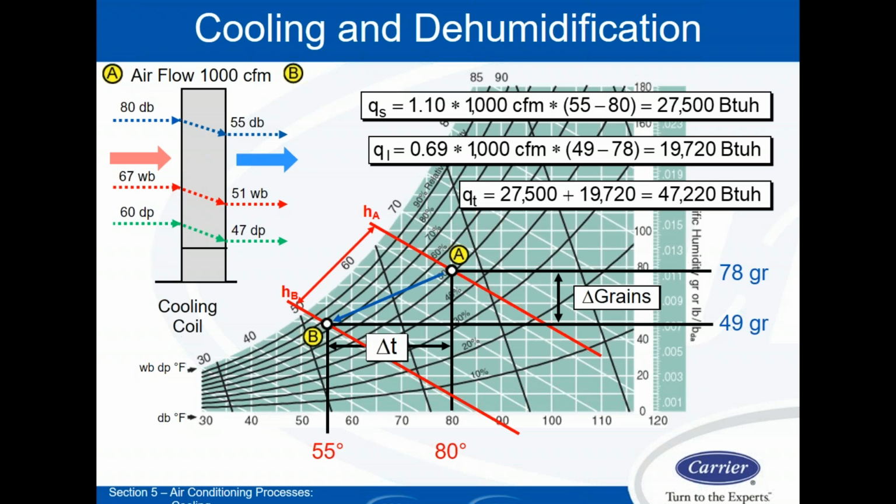Here's a completely loaded question from Paul. How often do rules of thumb regarding CFM per ton roughly equal the math you've shown here? So the CFM per ton is in fact slightly different than what we're doing here. In this case, we have an example with 1,000 CFM, and our total tons of cooling is 4.7. So that's 472 CFM per ton. That is on the higher side for mostly what we're doing.